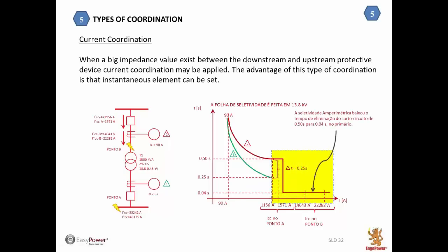The big advantage of using this is that when I set the instantaneous here, our coordination time is reset. We can start counting the time again. In other words, for the upstream relay above our primary relay, I can choose the coordination time interval above the instantaneous time.